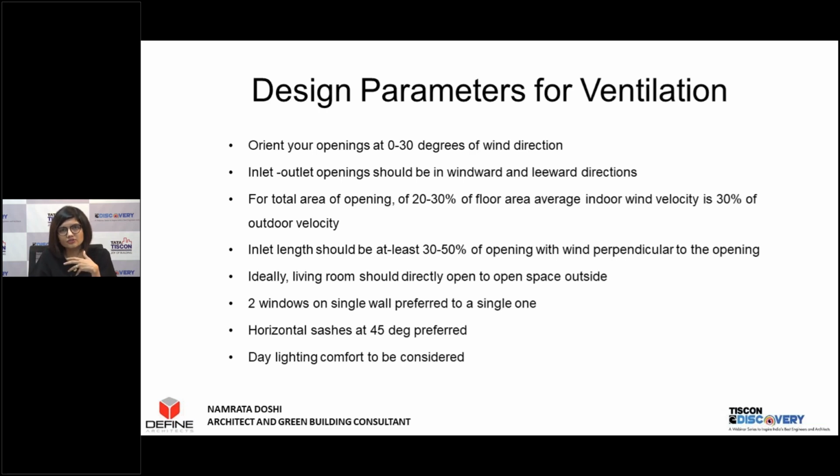In such cases, if you are facing a scenario where you don't have an extra wall to give an opening, like I mentioned during the kitchen discussion, try to have two openings. When you don't have that, it's preferred to have two smaller openings rather than taking the bigger opening. So you should take two smaller openings, balance your length, balance your area, but give two openings.